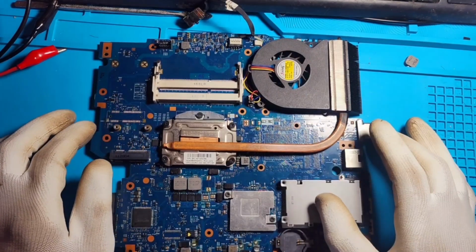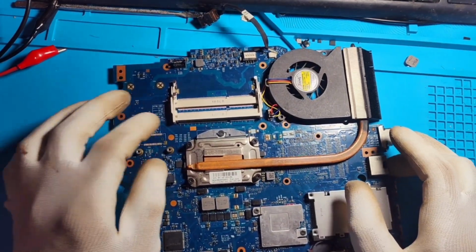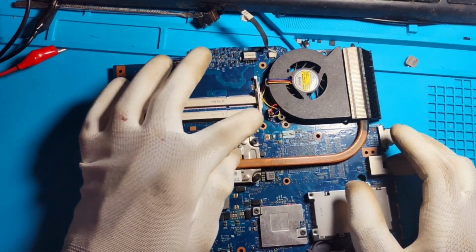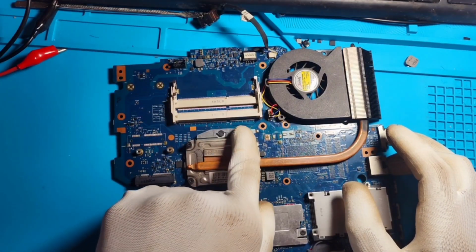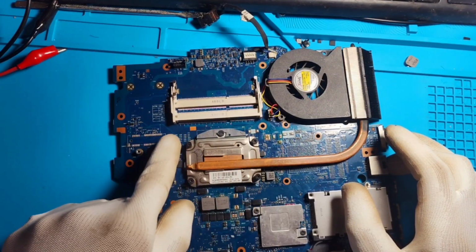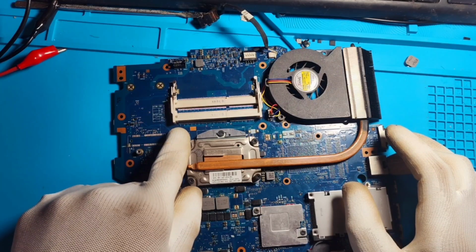So then I decided to check on the RAM side, on the RAM slots, so we can check the DRAM reset on pin number 30, and we can also check the system data and system clock line.